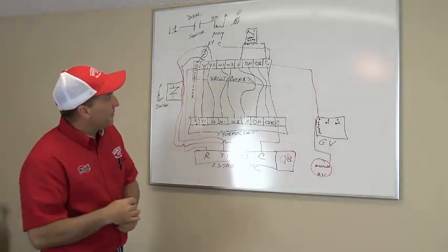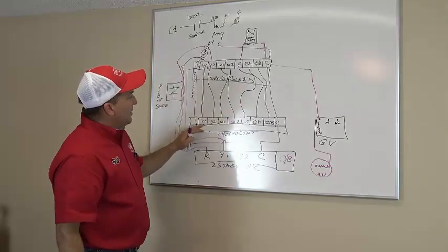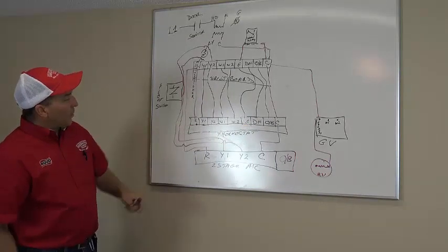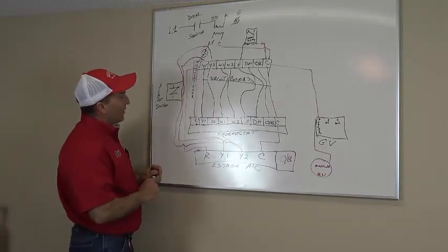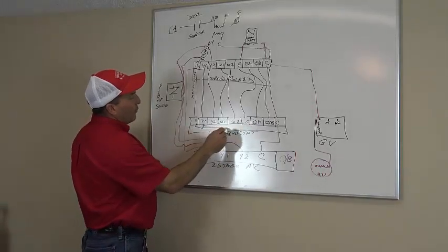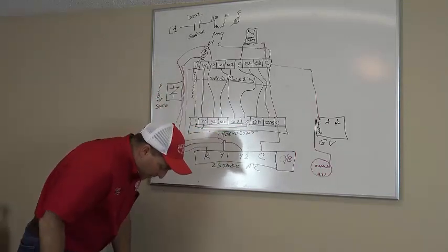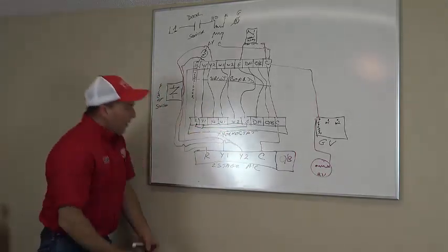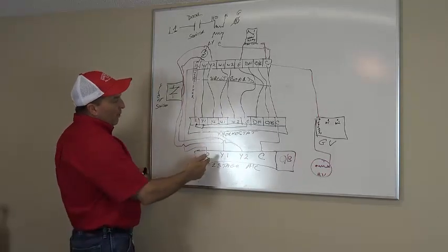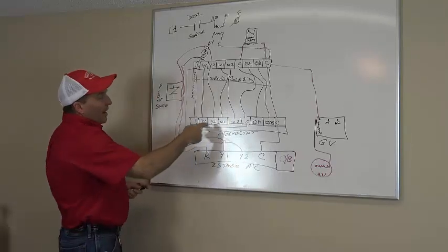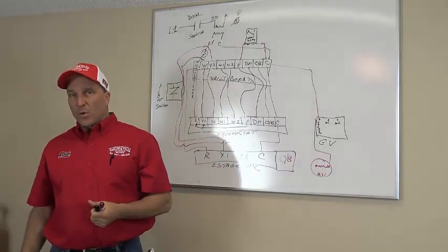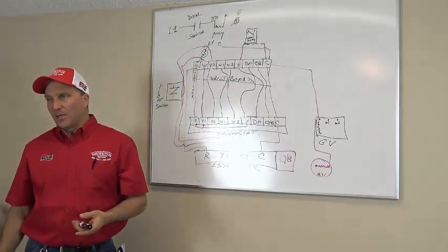Make sense? Okay. So at this point in time, nothing is on, right? So when we go and turn the air conditioning system on, we will energize R to Y1 over there to G. Now my air conditioning system is energized, right? And we're coming down to our circuit board at the bottom, in this case, which has a Y1 and a Y2. Well, right now, is my second stage energized? No. When do you energize second stage? When does it come on?